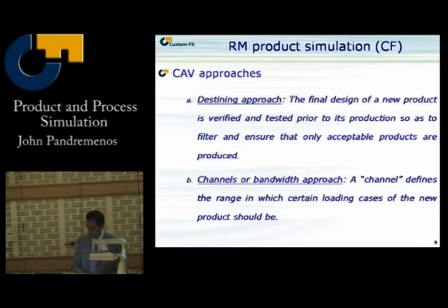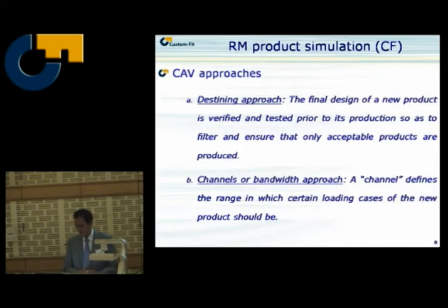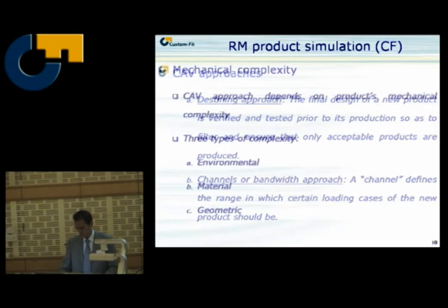The third approach, the iterative, is an automated product design process where the verification results are fed back into the design system so as to improve the design. An advantage of this approach is that it generates only certified products. The final approach, the analytical one, uses analytical relations between loading situation, material, and product geometry in order to make the verification. These systems, again, only produce acceptable copies.